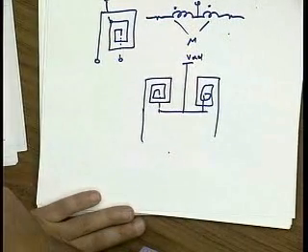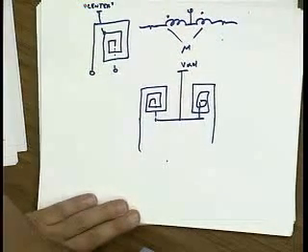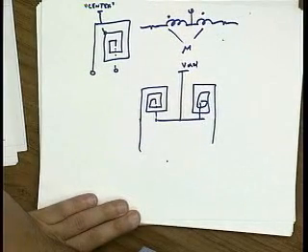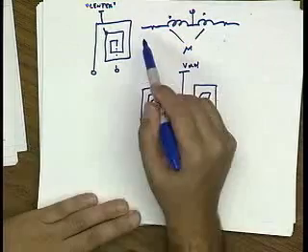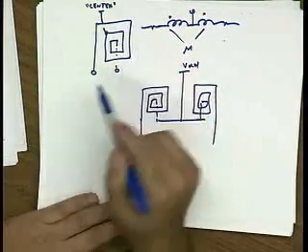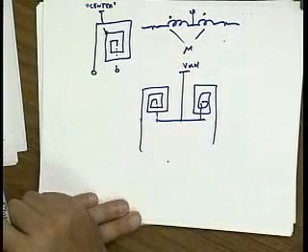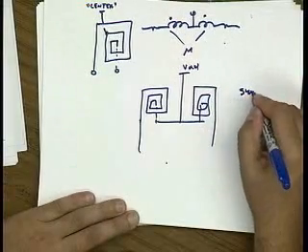Yes, Firas. So the resonant frequency is the one determined by LC or L over 2C? Yeah, it's L and C together, yeah. Like the complete L, right? Exactly, yeah. So you can think about it, I'm going to put a capacitance in parallel with this, and that's going to resonate with this total inductance. Okay? So this is one approach. This is now, at least it's symmetric.